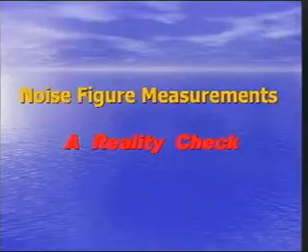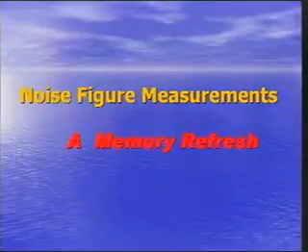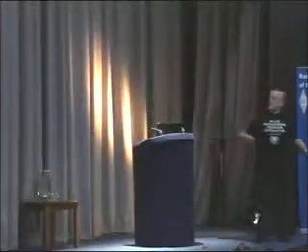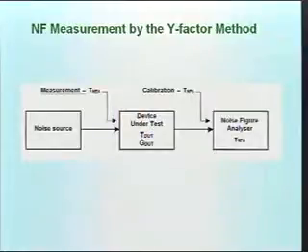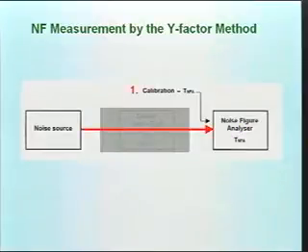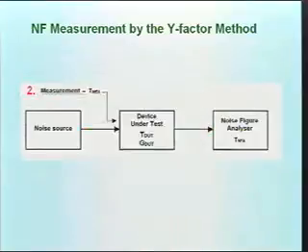So the alternative title is a memory refresh. I'm going to move through this quite quickly. We're all fairly familiar with the Y factor measurement that's used in most equipment. You have the noise source, the noise figure analyzer. Between them, you put the device under test. You begin by connecting the noise source directly to the noise figure analyzer for calibration, and then you move on to your measurement with the DUT in place.